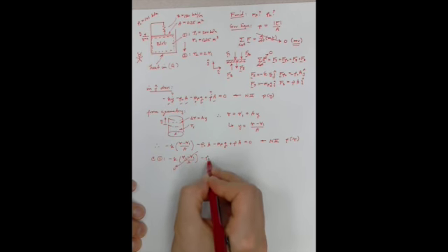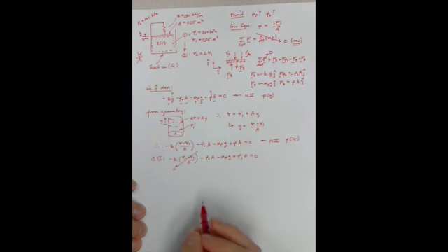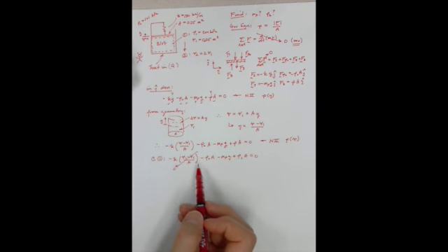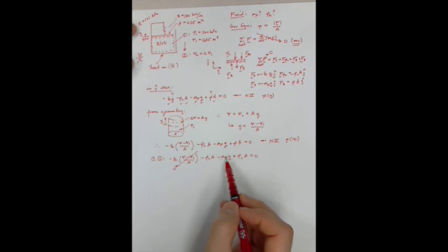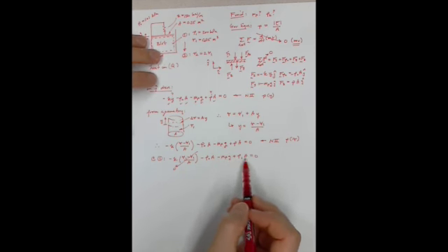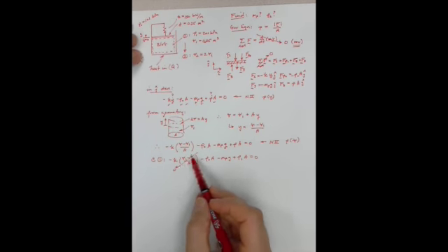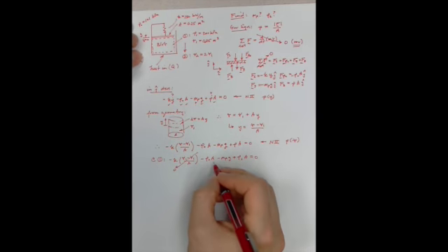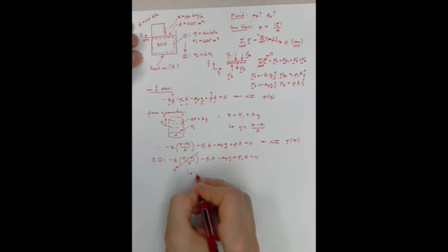And then I'll have P naught A minus mass of the piston, gravity, plus, and now P1 times A equals 0. So at the initial state, I have a mechanism by which atmosphere is forcing down on the piston head, and gravity is pulling down on the piston head, and the blob is pushing up on the piston head, but the spring force is precisely canceled at this point. It's 0. And happy day, I know everything in this equation except for the mass of the piston.